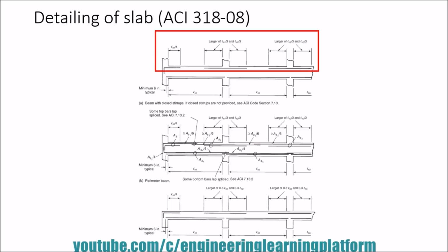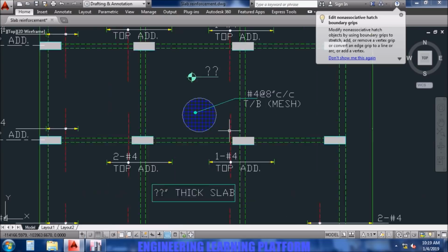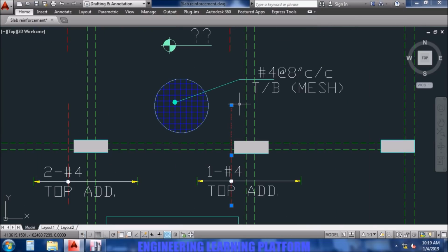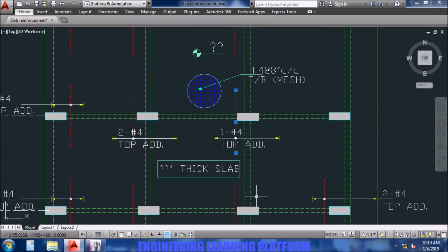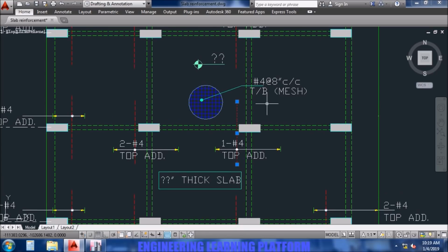The development length is provided so that the bar is properly anchored within concrete when cracking occurs. So the extent of this red top bar is at least 1/3 of the span in both directions. The longer span is preferred for the bar length, which was adequately placed by my draftsman.